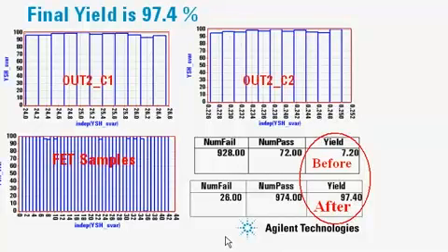Okay, these statistical tools that we have discussed have helped us find the problem in our initial design, fix it, and raise the yield from an initial 7.2% up to 97.4% before going into manufacturing. Notice here, with the new, final design, if we run yield sensitivity histogram on any of the components in the design, we see that it has no variability, no sensitivity, and the yield is very close to 100%.